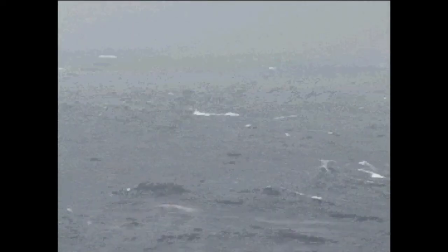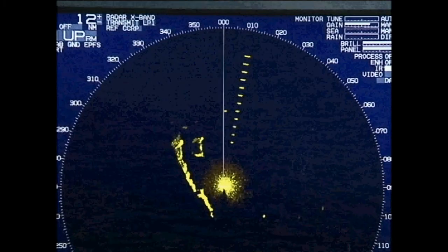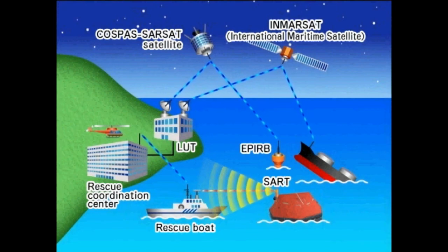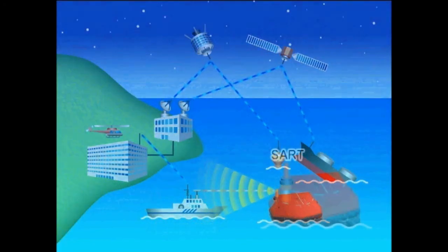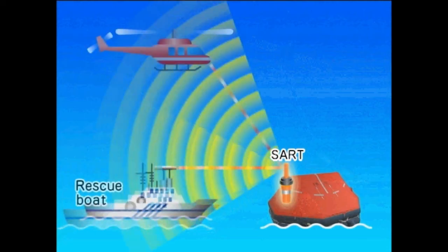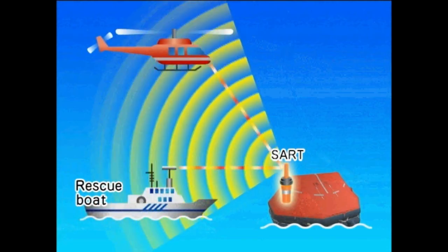Ships and/or seafarers in distress are often caught in rough seas, making it difficult to detect lifeboats or life rafts merely by sight or radar. SART is valuable because it allows easy detection of the accident site using a radar display. EPIRB distress signals can be received anywhere in the world via the Cospas-Sarsat satellite system. SART is used by other ships in the area to approach shipwrecked people awaiting rescue.